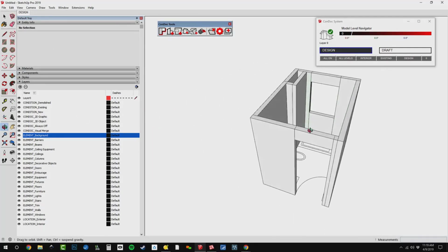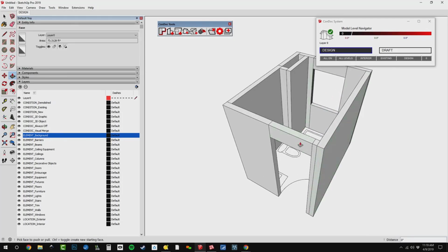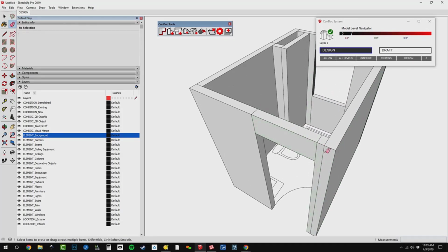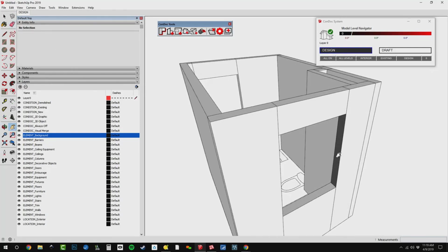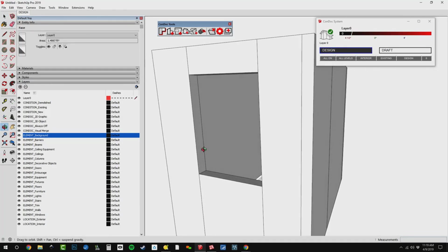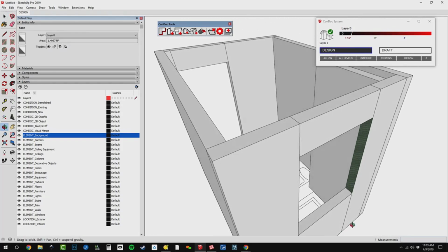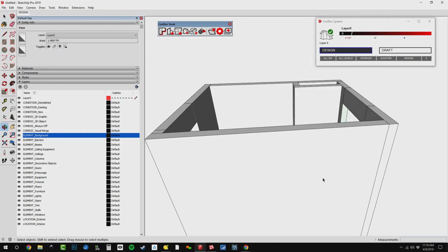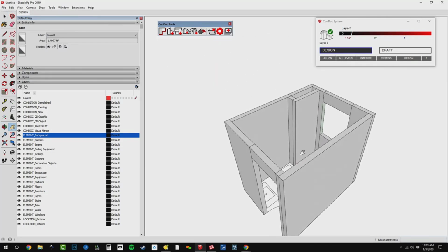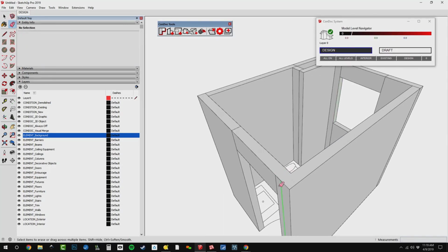We've got all of our walls, and we have all of our openings. Now, we do need to clean up this geometry a bit. And so I would go around with my eraser tool. You know, this guy turned itself inside out. Sometimes that does happen. Pretty easy, just right click and reverse that face. Not critical, but I just like to keep things super clean. All right, so normally I would go through and start erasing all of these edges.